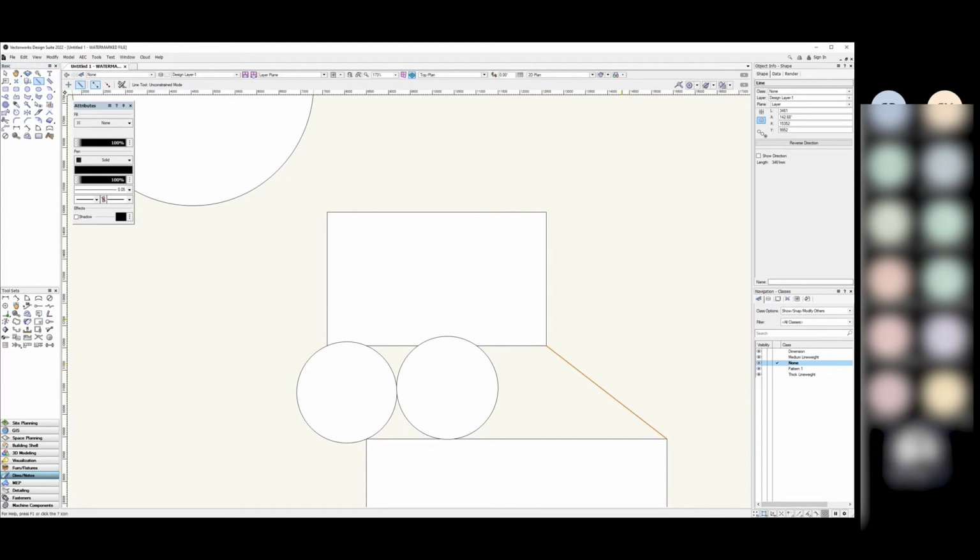So I would say play around with some of these snaps just in your own time. The useful ones that I quite like are snap to object, so you can snap to the corners and middle points and stuff of objects. Snapping to angles can be useful. For instance, if I bring it out to the right, that's an angle of 0. If I bring it up, it's going to snap to 30, then 45, then 60, and then 90. So it will snap to the most common angles. If you don't want it to do that, just turn off that angle snap and it will turn off.